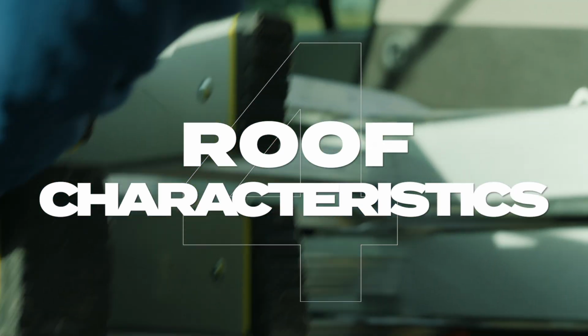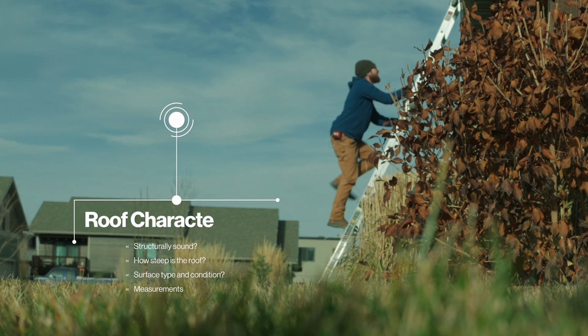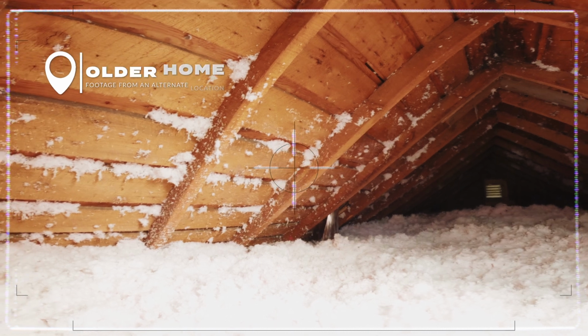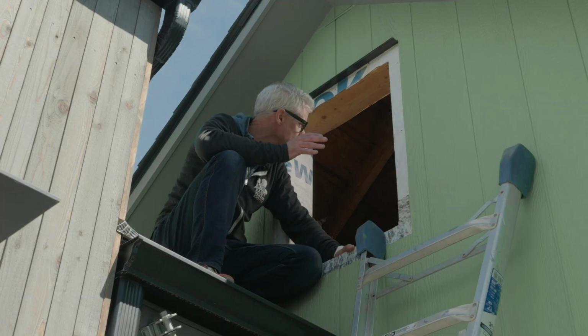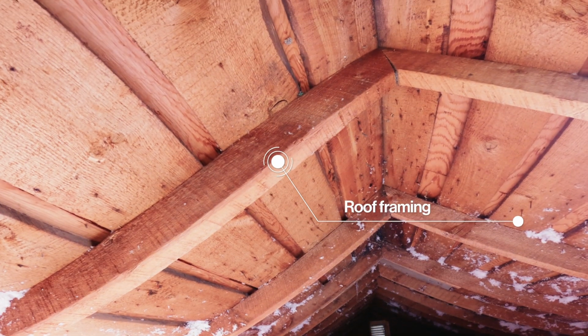You'll spend most of your time assessing the roof for structural integrity, ease of installation, and overall condition. It's also the right time to verify the system size before we take measurements. When you're in the attic looking for insulation and air sealing opportunities, you'll also want to take a peek at the framing to make sure it's structurally sound to put panels on. To be safe, we're looking for stamped engineered trusses.